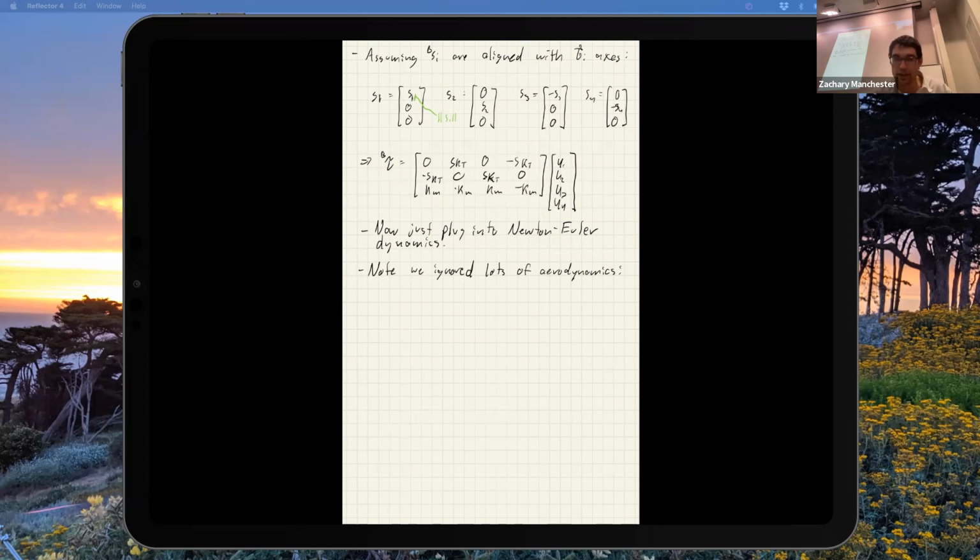If you're doing crazy aerobatic stuff, body drag, wake and boundary effects are another big one. Has anyone ever tried flying a quadrotor near the floor? This actually came up in our seminar talk on Friday. You get what's called ground effect, or just boundary effects. Basically, you get this cushion effect from the air bouncing off the floor if you're close to the floor, and that actually increases your lift. So that's kind of interesting. Same thing with flying near walls. You get weird boundary effects.